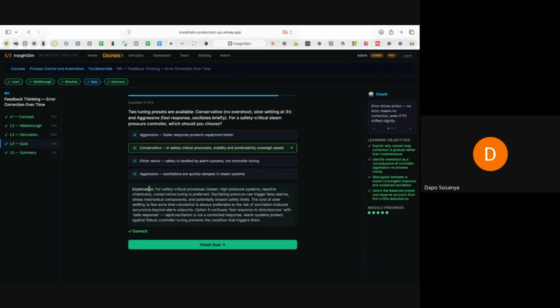When I say that the setting you use depends on your process, conservative is preferred for safety critical systems, steam high pressure systems, reactive chemicals. For such critical processes, it's better you are conservative, because oscillating pressure can trigger false alarms.